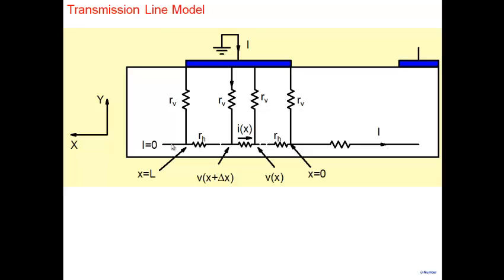So you can imagine the current at this particular point would be 0 because the currents are originating from here. So the current here is 0, and then the current here will come and the current here will come. So gradually Ix will build up, starting from a value of 0, and reach a maximum value here. And then we'll enter your device. Your real device starts from here. Okay. So all these currents are coming in and joining together and building up, and finally the full current flows here. Okay. So we would like to find out what is the overall resistance of this particular contact.